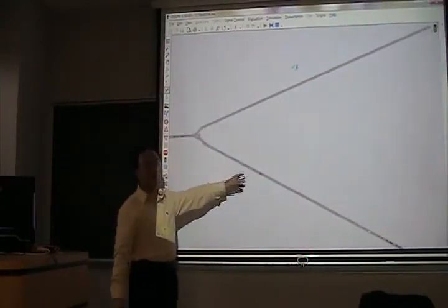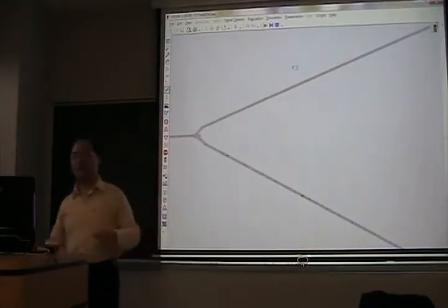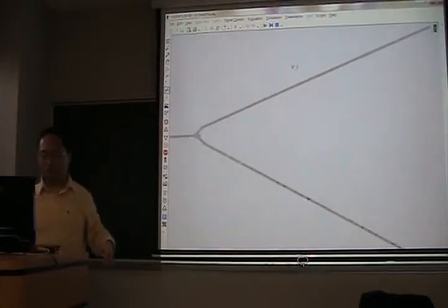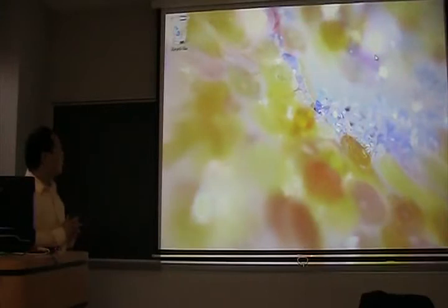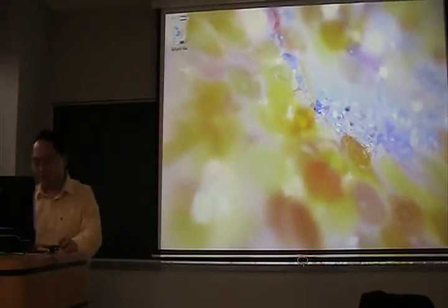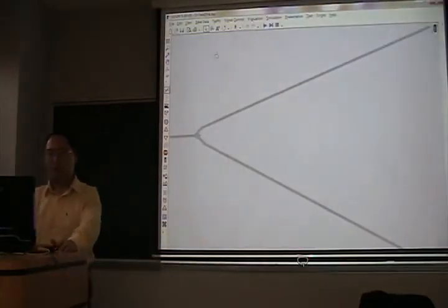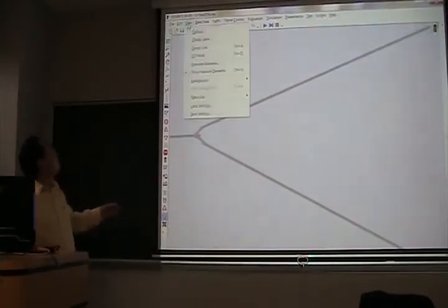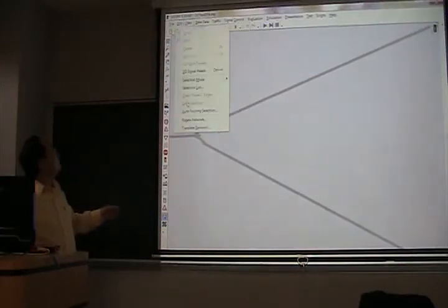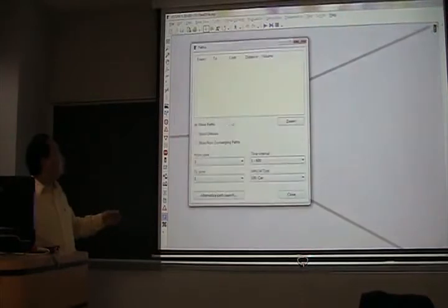So in the second iteration, you see vehicles are all going through the lower part. So minimize it. So it's done. And if you click this parking lot button, you will be able to use the edit auto routing selection function.